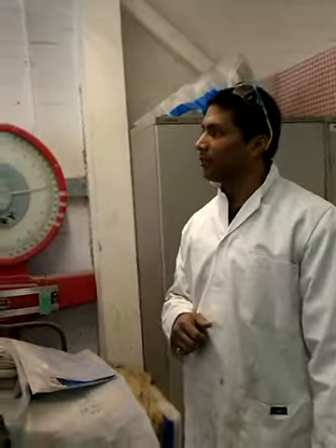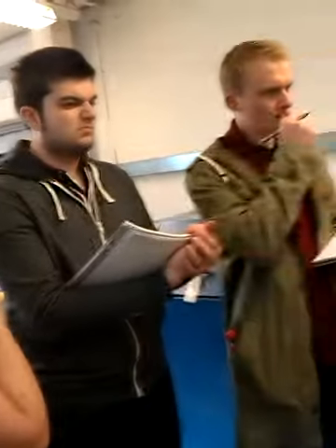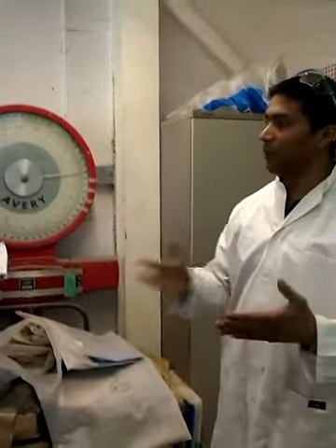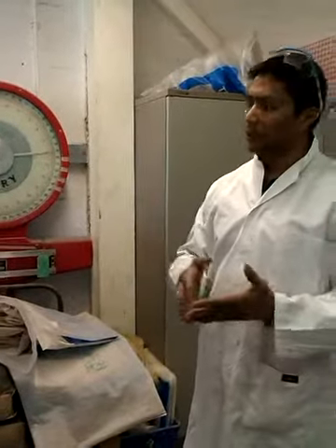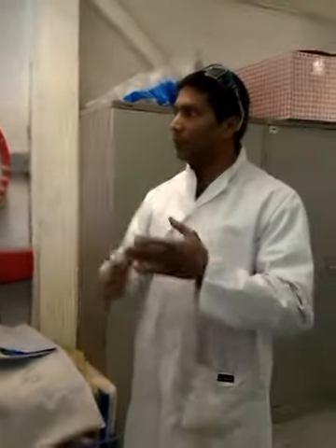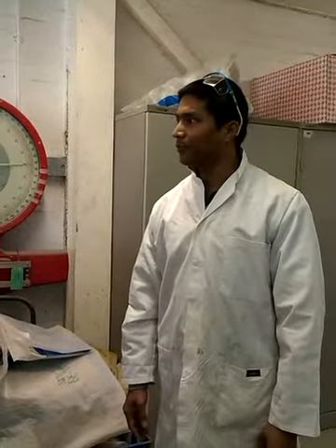Also, the rebound hammer. So you use the rebound hammer in both then. Yes, you can. Normally, it needs to be done on both ends, right? And needs a minimum of 9 readings. We have got only 3 because of time, just for an idea. And from 9 readings, you will get an average, and from that you will find out the hardness of the concrete. Okay, right? Good. Okay.